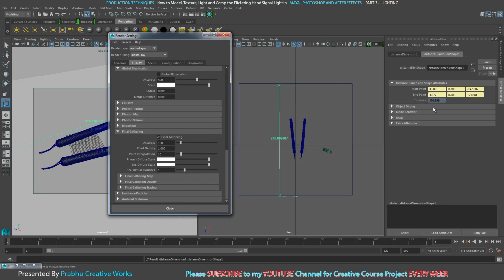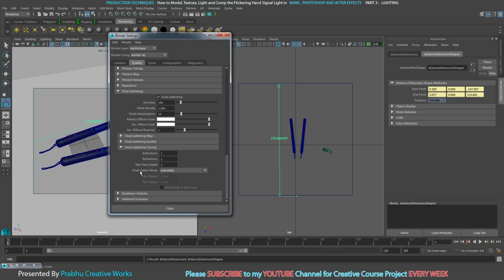If you have anything above or below this value, you want to calculate that one. It's my scene size, so it depends upon the scene size. Don't keep the exact value that I did. If you have 300, you want to go through that. So go to final gathering, and set the final gathering mode to use radii control. Here you give the maximum radius based on your distance size.